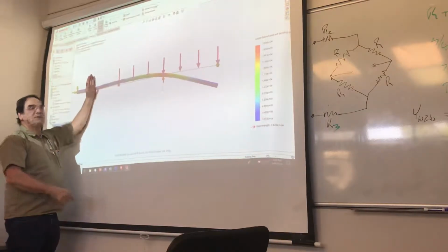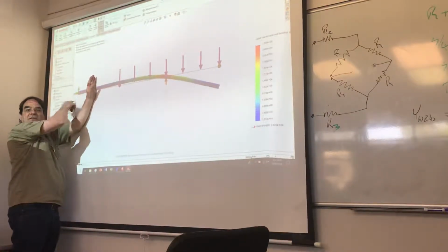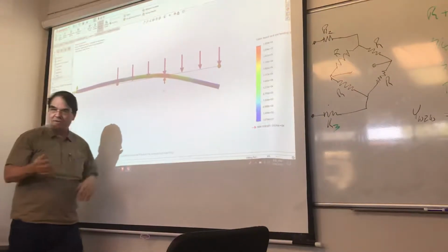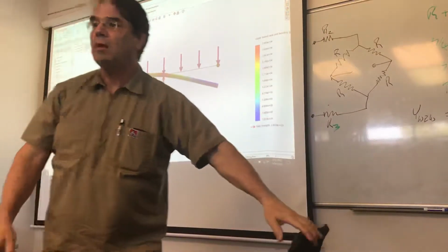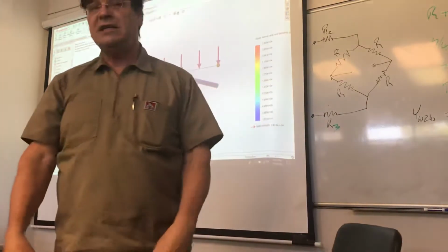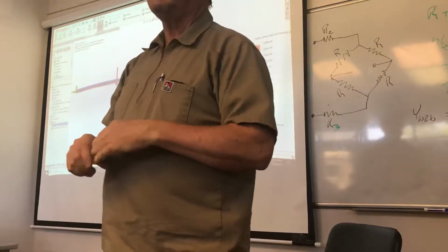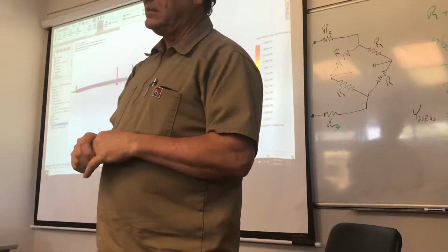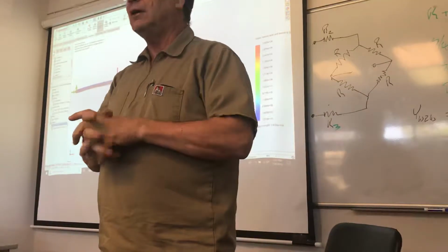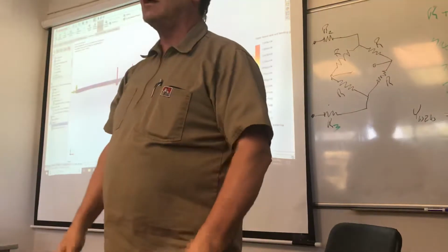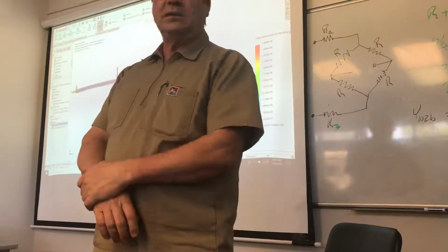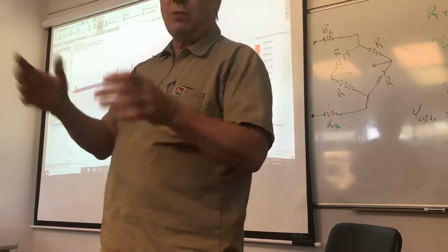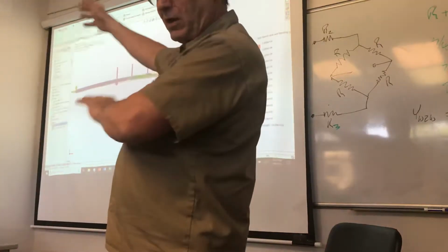Right, so all you're doing is fixing it and trying to figure out what the stresses are from the loads applied at the immediate location. That one's where you have to model it as a solid, or at least shells. I would probably model it as a solid these days, it's easier. I don't think the answer is as accurate, but it's easier. So okay, we'll do it the easy way. Does that make sense?